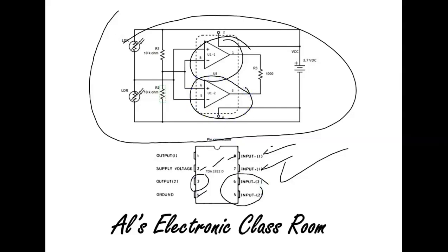So you can see from the video when we shot pin 6 and 7, and again, maybe that's not correct, 6 and 8, what we're doing here with this package is connecting the plus input of U12 to pin 8 of U11.